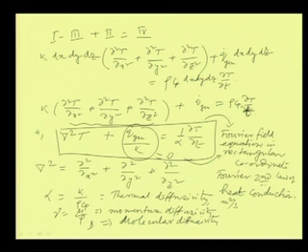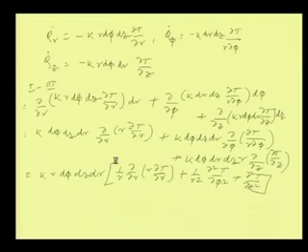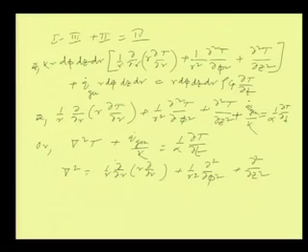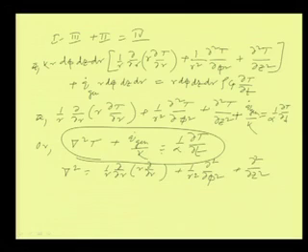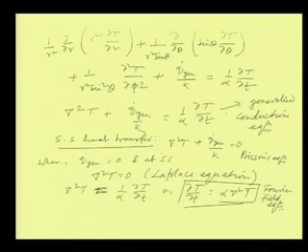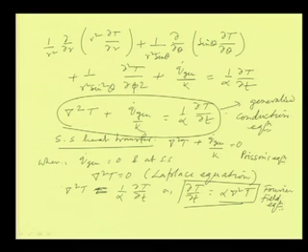But in general, the whole equation is called the general heat conduction equation, which we have seen for all the cases, like in cylindrical coordinates and in the spherical coordinate system also. But the Fourier field equation is this equation when the generation rate is 0, there is no heat generation within the body.